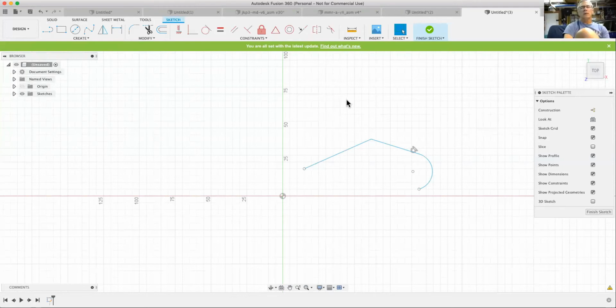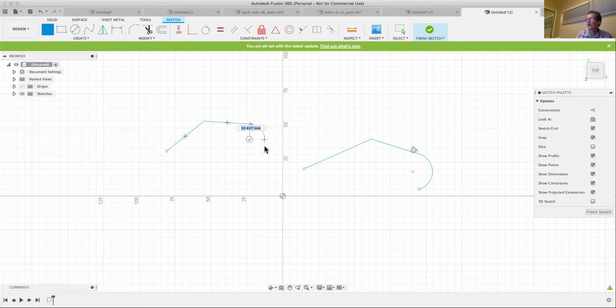When you said hold, did you mean hold your mouse button down? Hold the mouse button down, yes. Okay. So generally with Fusion 360, it's sort of a click, not a click and drag. That's one of the exceptions. So click, move to make a line, click, another point, click, another point, but click and hold and drag gives me the arc. And then a click finishes it. And here's another line. If I go way off, it'll be non-tangent. If I'm close to tangent, it'll snap to tangent. And then I'll double click on my endpoint, and then I'm done.